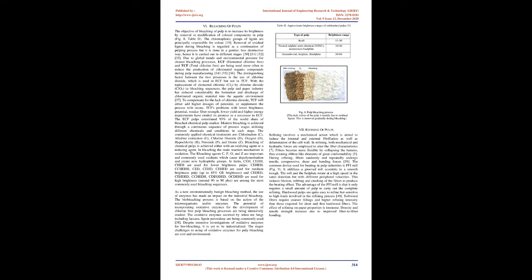The RMP process involves defibration of chips in a disc refiner under increased steam pressure. The process involves two refining stages in series, producing a longer fibrated pulp than conventional groundwood. The pulp is bulkier, stronger and contains fewer fines. The mechanical properties are also better, but the pulp is darker in color than SGW.